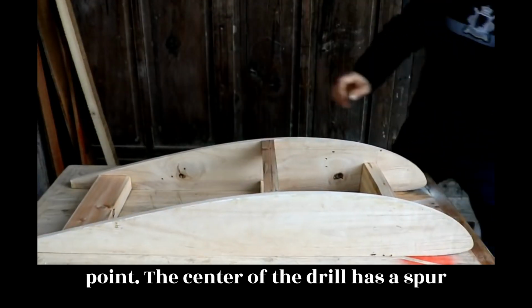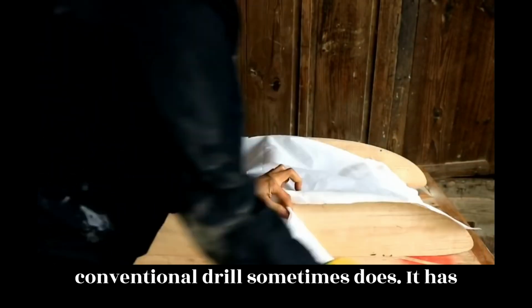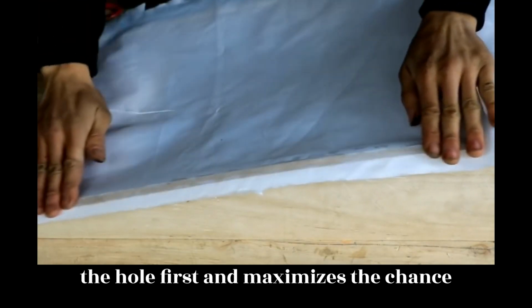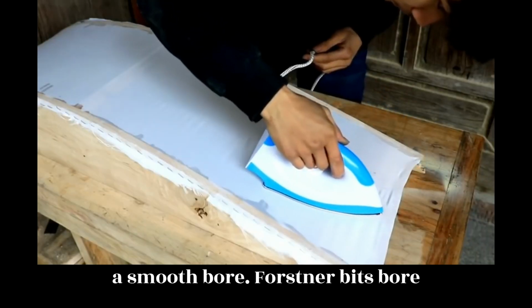The center of the drill has a spur with a sharp point and 4 sharp corners to center and cut rather than walk as a conventional drill sometimes does. It has the outside corner of the cutting edges leading, so that it cuts the periphery of the hole first and maximizes the chance that the wood fibers cut cleanly, leaving a smooth bore.